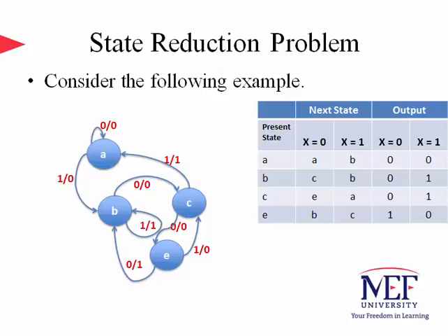Finally, we reach the 4-state state diagram whose state table is shown to the right of this slide. As can be observed, there are no redundant states at this reduction stage, so we stop. If we draw the simplified state diagram, we obtain the diagram drawn to the left of this slide. As you can see, the state diagram is dramatically reduced to a much simpler form. It is easier to work with this state diagram when we design the synchronous sequential logic.